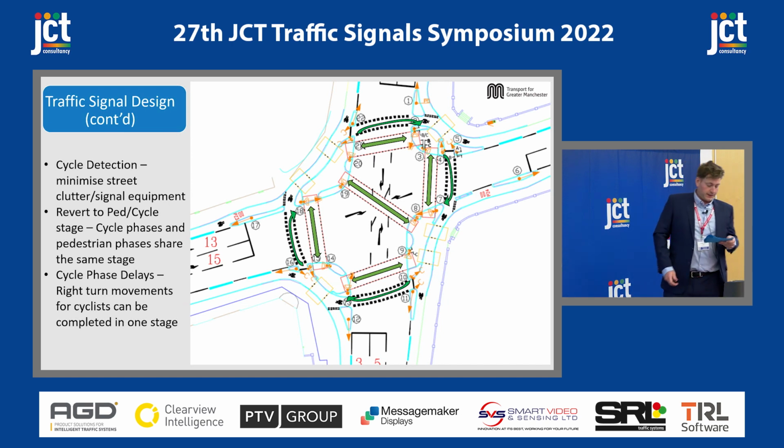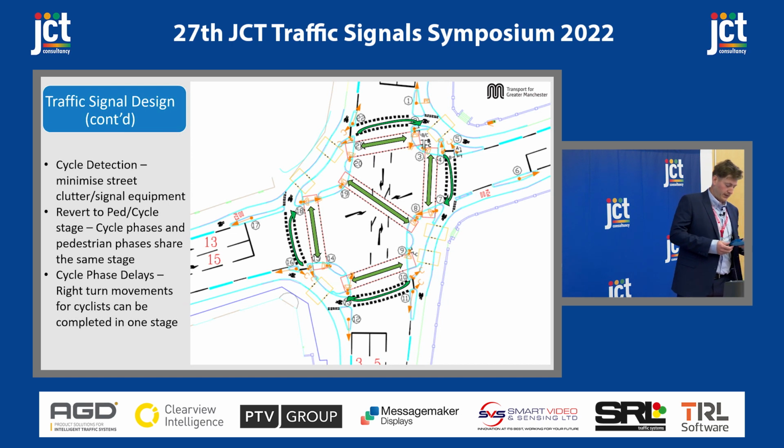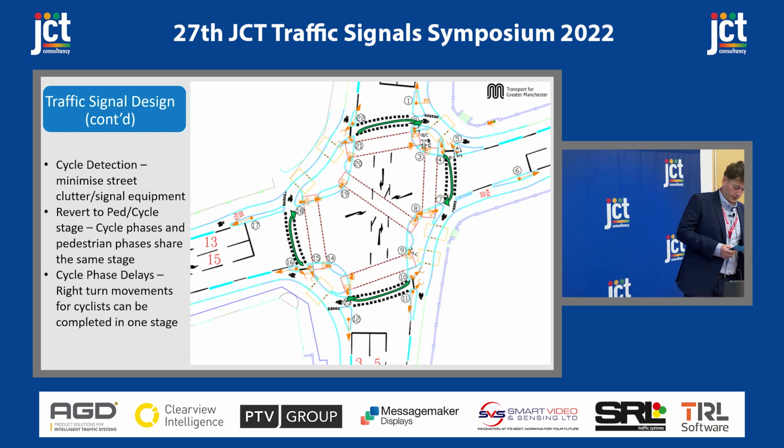Also, cycle phase delays. Because cyclists travel at a higher speed than pedestrians, these can be used to extend the cycle phases beyond the end of the combined pedestrian and cycle stage. So you can enable cyclists to make right turn movements through 2 phases over 1 stage.